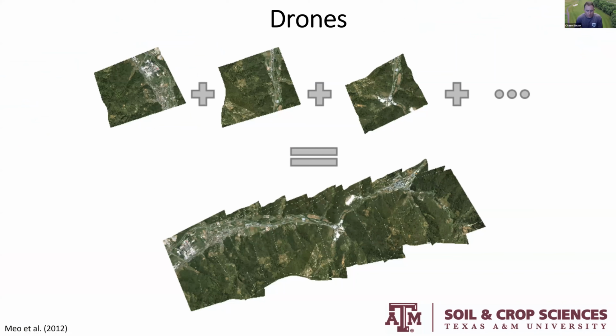Typically, the way a drone works is you fly your course, it takes frequent images, and then you use some kind of software to stitch them together to create what's called an orthomosaic, which is just this compiled image. Anybody who's ever had a drone fly at their course will notice that the edges of your image are kind of rigid. It's because they've stitched together several images to create the one, which in itself can introduce some accuracy error, but nonetheless, it's still somewhat accurate. And then you can use ground control points to geolocate and be sure geographically your images are where they're supposed to be.